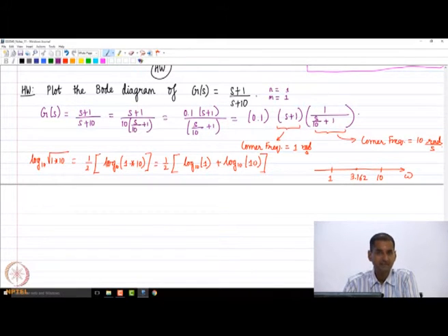It is, right? By the way, I think I should highlight this point. There are two groups, or two ways, in which people look at a minimum phase transfer function, or minimum phase systems. Some people associate it only with zeros, because they implicitly assume a stable system to begin with.